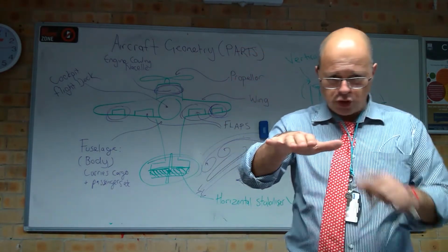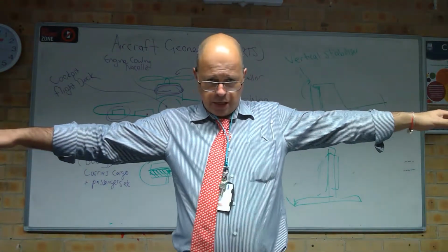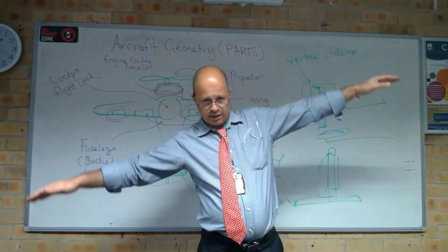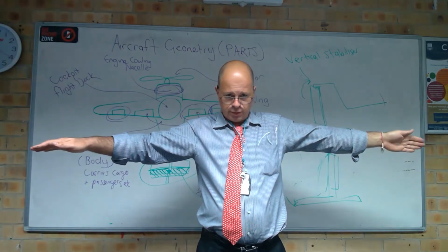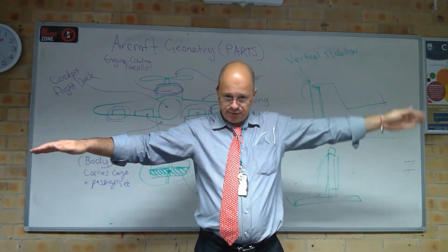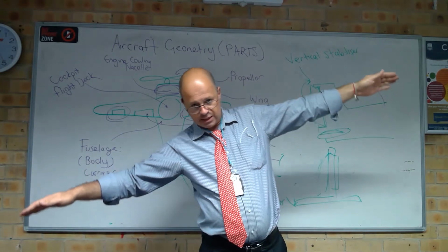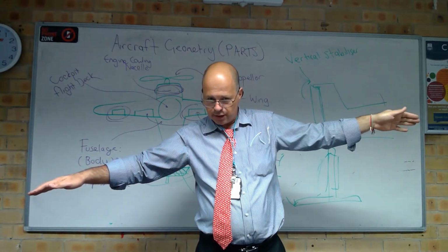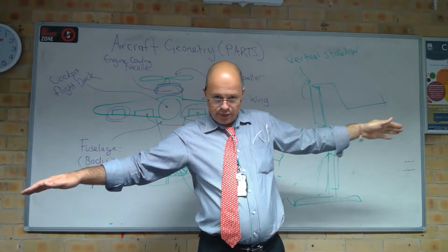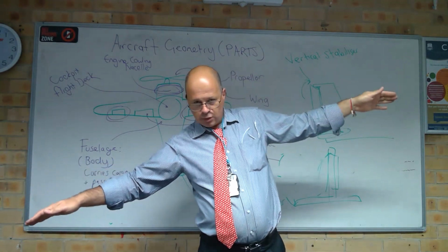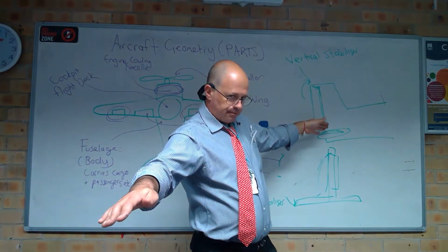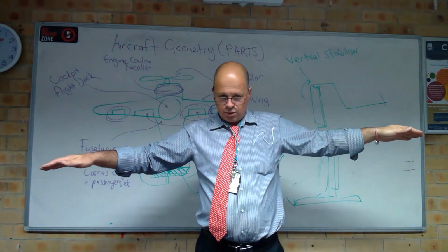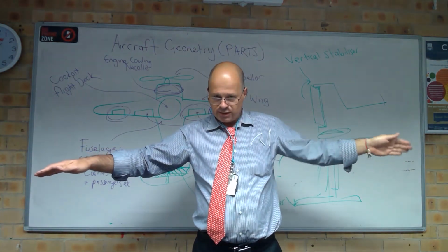So normally, if you've got an aileron, if I was banking to the right and I just drop this one down, I'm increasing the lift here, which is great. So I'm going to start to roll. The only trouble is I'm also increasing the drag on this side. So if this wing's slowing down, even though I'm rolling this way, I'm going to yaw that way. Okay, think about it. Increasing lift, but increasing drag as well.